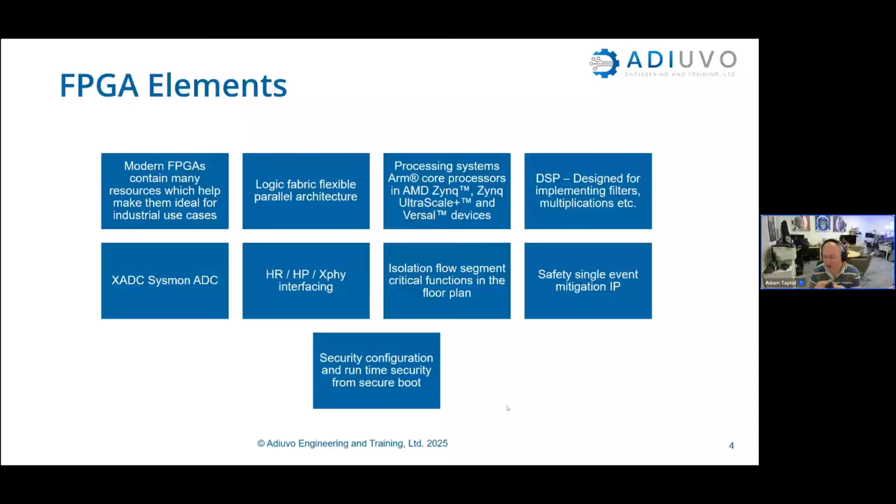We have a range of I/O, and we touched on it briefly a minute ago when we talked about the any-to-any connectivity and communication standards. But it really is important to dive a little bit deeper in and take a look at it. So we have the high range FPGA I/O, which is going to give us 0 to 3.3 volts, and that's going to allow us to interface to some legacy sensors and some slower speed sensors. Things that connect over SPI, I2C, for example. Accelerometers, pressure sensors, things like that. We can use the high range for.